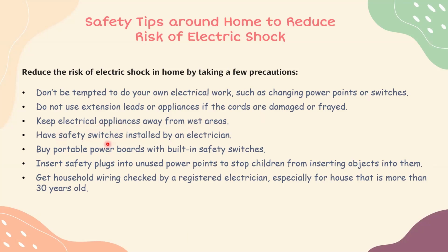Have safety switches installed by an electrician and only purchase portable power boards with built-in safety switches. If there are children at home, safety plugs need to be inserted into unused power points to avoid children playing with them. Lastly, hire a registered electrician to check household wiring, especially for a house that is more than 30 years old.